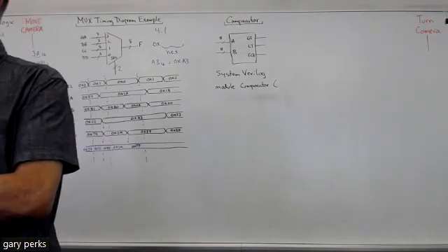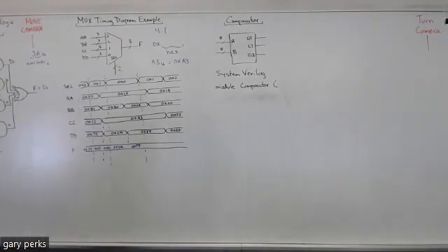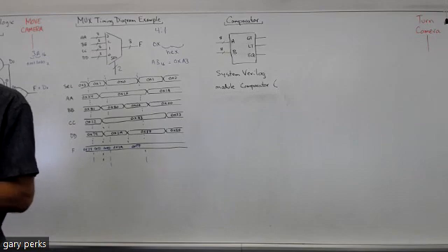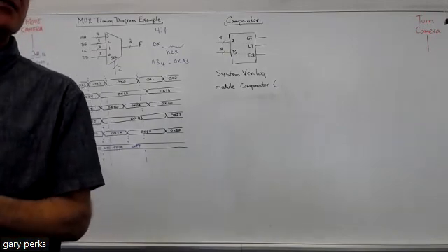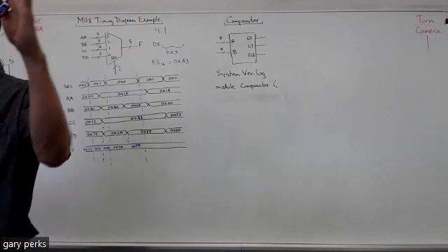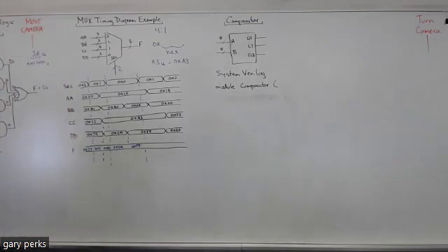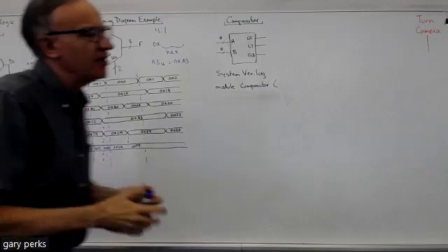See, the big difference between the two is that the code that represents hardware can have parallel functionality, just like a circuit does, where instructions to a microprocessor are: do this, do that, do this, do that. So you see, with Verilog, you're modeling hardware where things can happen at the same time, because that's how hardware works.